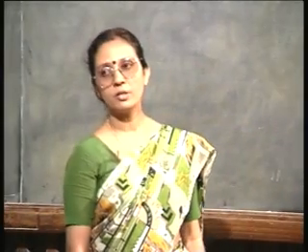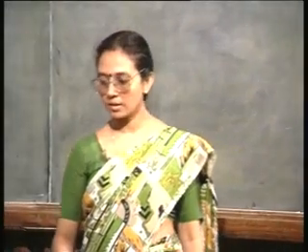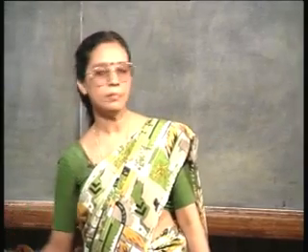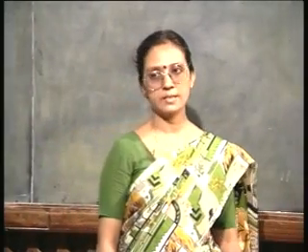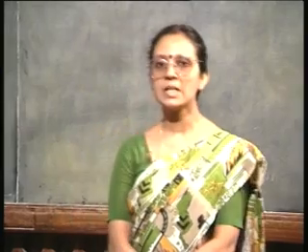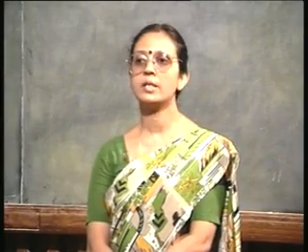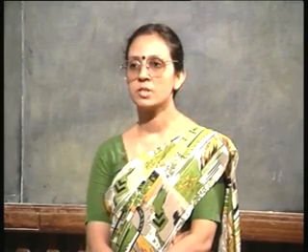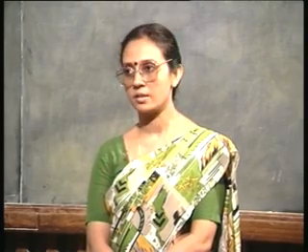Zone refining is nowadays quite popular. Many of the vendors sell these FZ crystals, and this will give you your semiconductor single crystal, silicon single crystal.